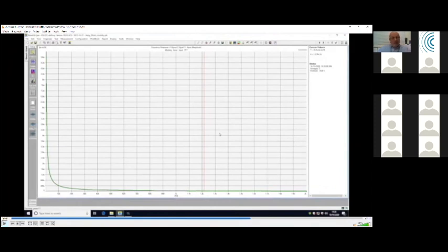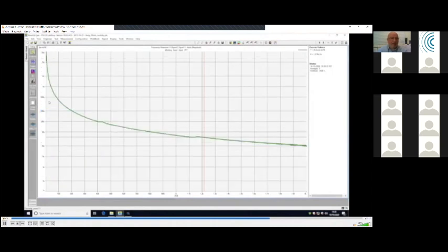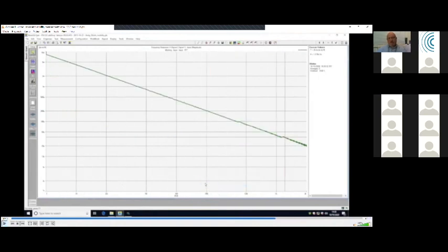Okay, so what we've got there, it's quite a simple plot, but it makes much more sense actually if we log both axes. So we're going to see the analyzer now log the y and the x-axis. So we've now got mobility on the y-axis. Yes, that's right. So let's see that. Log, there we go. And if we do the second log button, so now you can see we've got a classic straight line mobility that is decreasing as frequency increases.